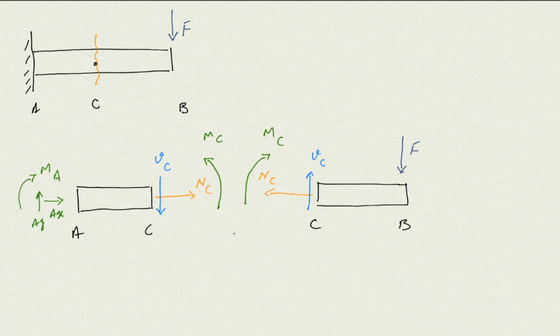And this is what we use when we want to analyze or do the example or calculate these forces. Make sure that you always draw them in a positive format and then do the calculation. So if it comes out positive, everyone knows that you mean this direction. If it comes out negative, again, everyone means that it is opposite of this direction.